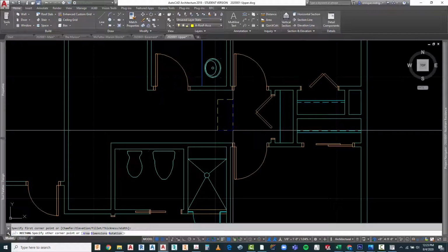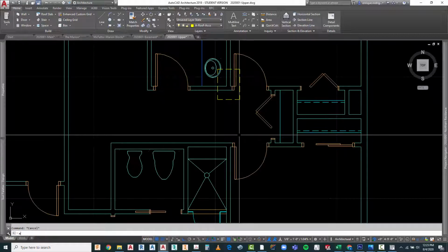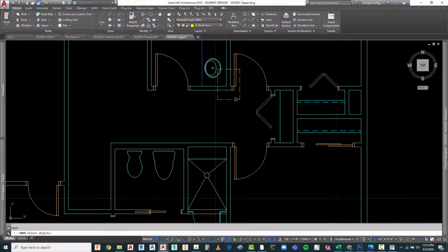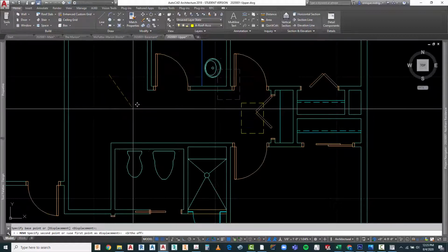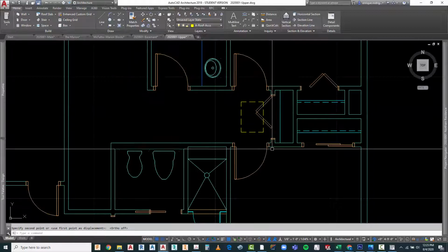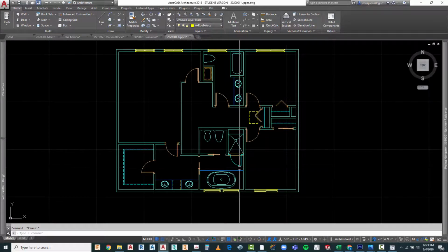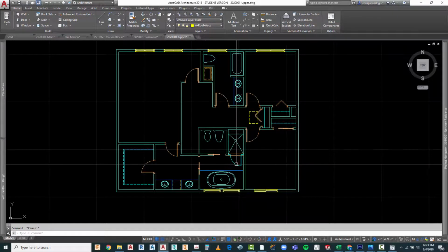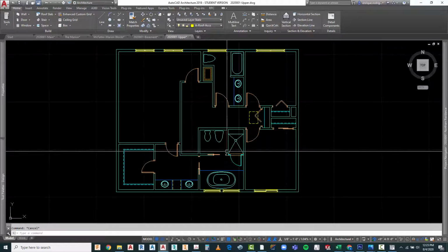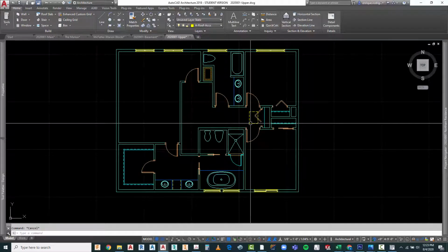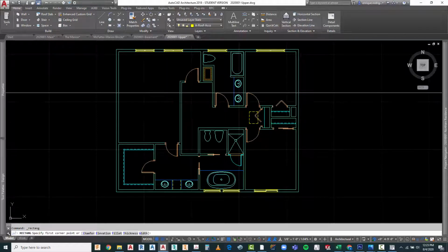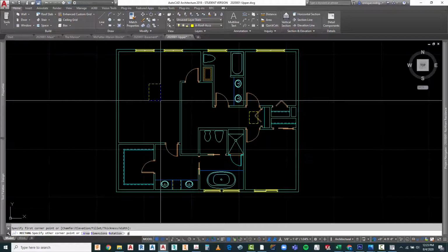And I'm going to go ahead and do 22, 30. And I'm going to place this where they show it. Place it sort of centered right there. And I'm going to go ahead and do the two skylights. Let's see, we got one 24 by 24 and the other one is 24 by 36. I'm going to leave it as a roof access for now. So we could create a layer for it later on, but let's go ahead and do this the right size,